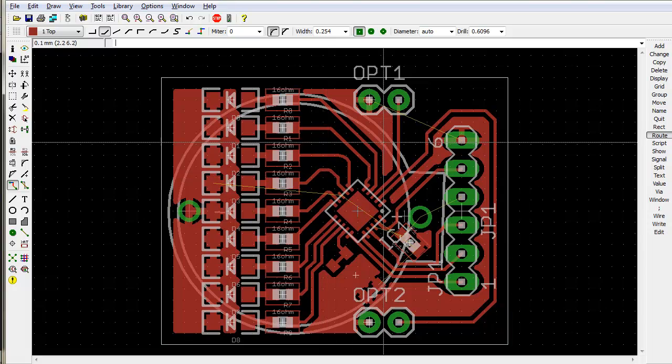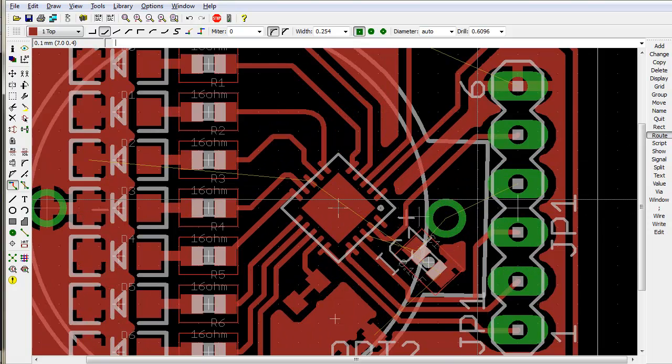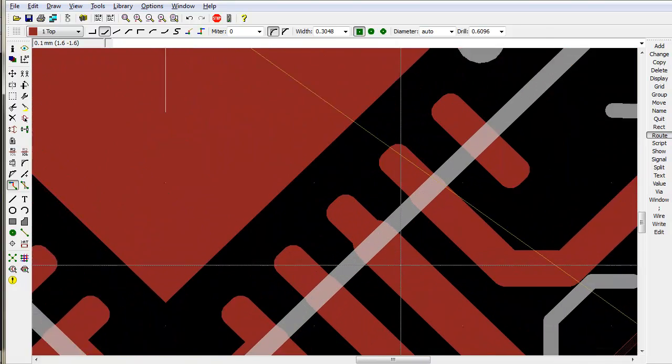So that's tightened in our Polygon as well, because it's basically cut off all of this area, so we may or may not want that. Now we've got the power to route here. It goes to this capacitor and comes out really nicely. It's a little thicker, so we're going to have to change that because it's a global size for the net class for the power, but it's too wide, and you can see here.